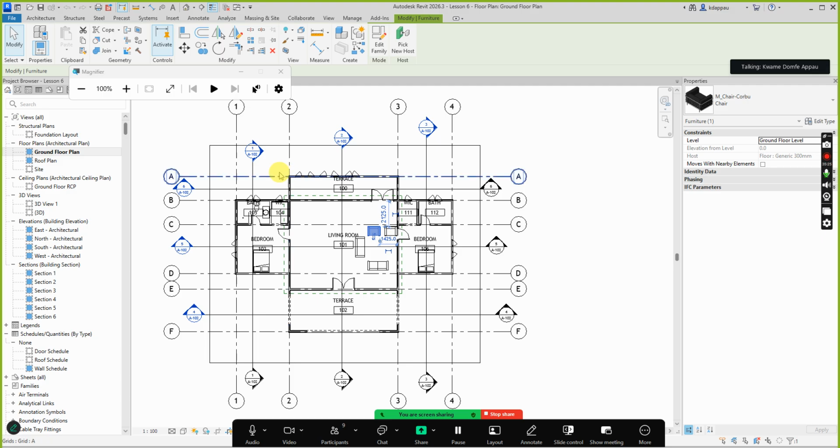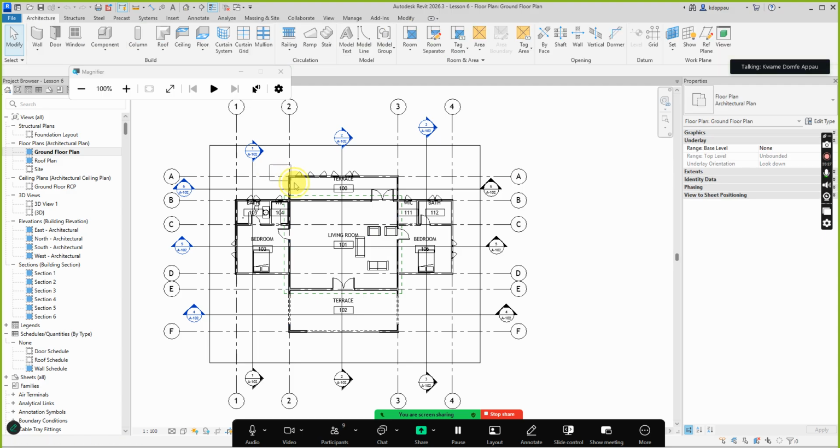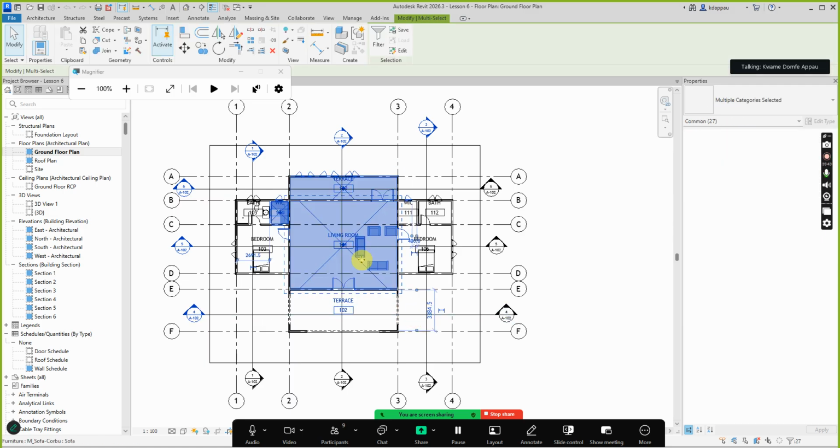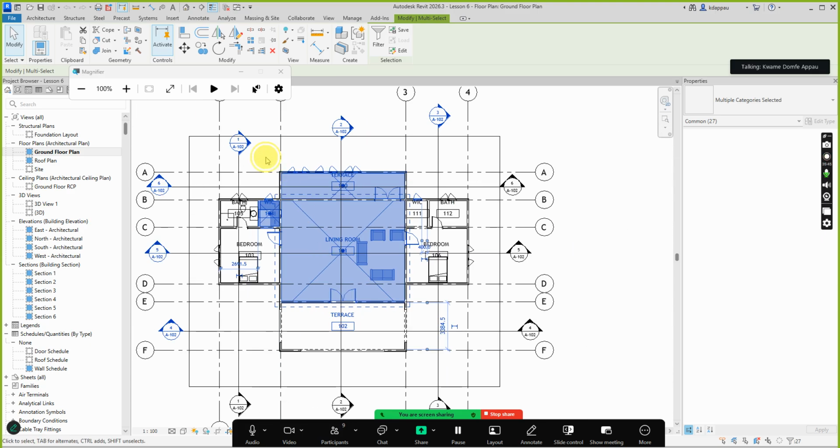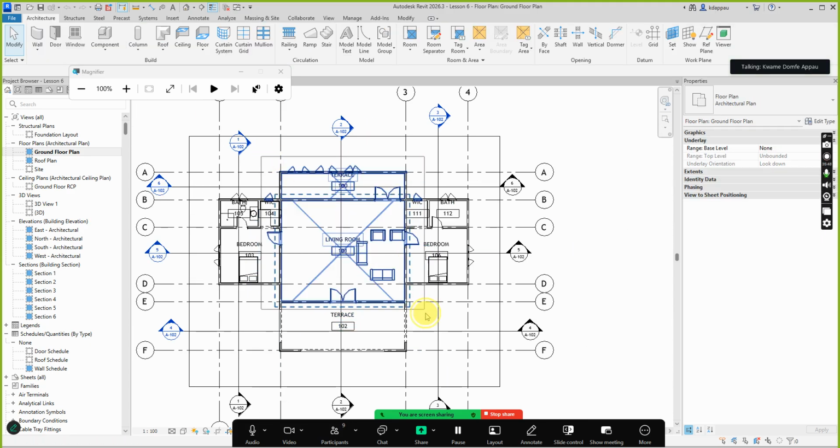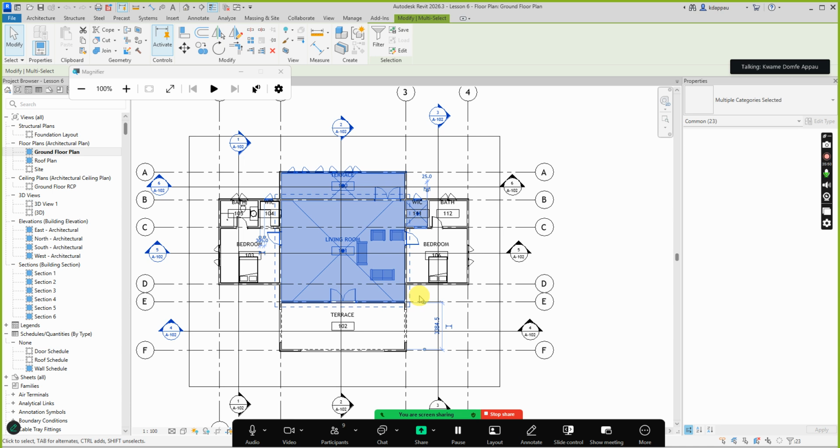You pick a point in the screen, then you drag your mouse down, lower left down. You see, you can drag your mouse like this one. You understand? When you drag the mouse, any object that falls completely within the window will be selected. So when I draw like this one, this way, and I draw all the way like this one, everything in the window will be selected. So that's one way of selection.